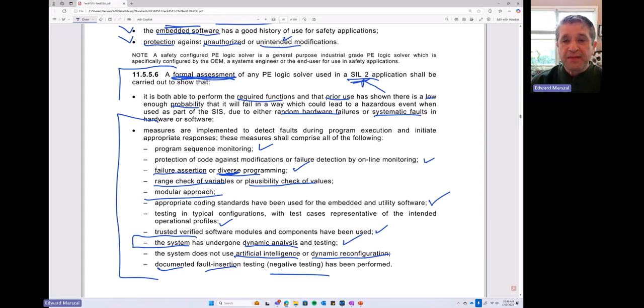Okay, now, what I will tell you, and I'm going to take a little bit of a step back here, there are a lot of devices that have a SIL 2 rating. Now, most PLCs that have a SIL 2 rating, I wouldn't consider them safety PLCs.